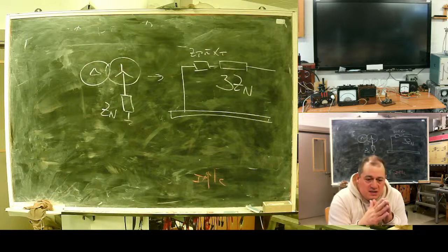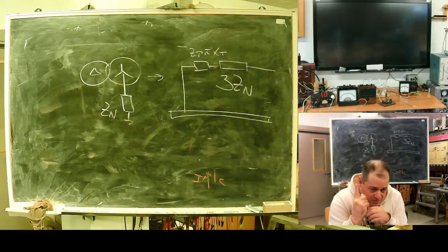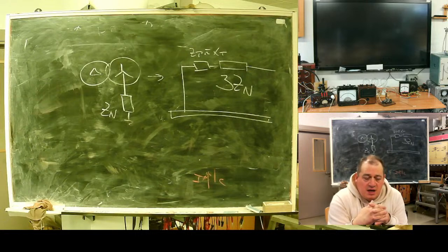For cable lines, it's not important whether it is an air cable or a ground cable. Reactive resistance is very small, something about 3 milliohms per kilometer. Active is determined by the material of the conductor and the cross-section of the conductor.